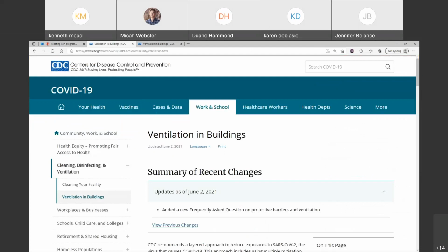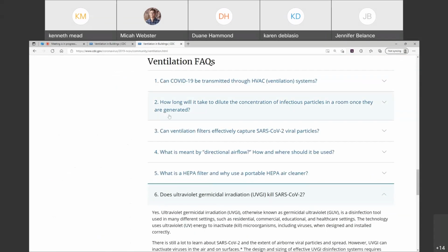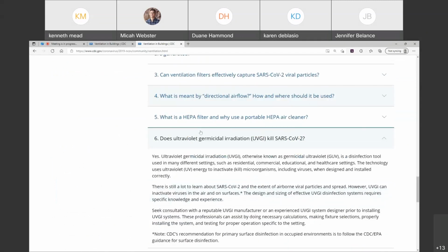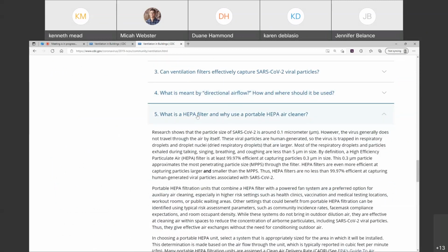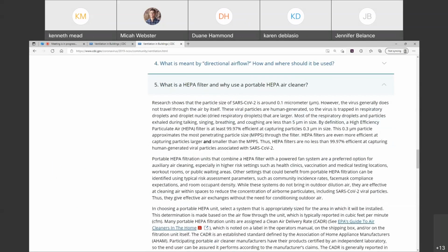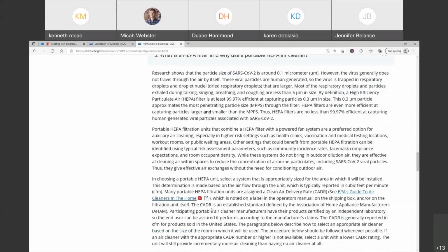I think I saw in the chat where you had been provided this link previously. So I'm going to jump over to the FAQ, and what we tried to do was to go into a lot more detail there. Part of these FAQs were driven by the kind of ventilation-related questions that were coming into CDC. All of these are potentially important to you, but I want to come down here in particular, where we have a conversation about the use of a HEPA filter and how to select one. In particular there's something called the clean air delivery rate. We don't have time to go into all of that now, but the guidance on how to pick a filter unit is there.